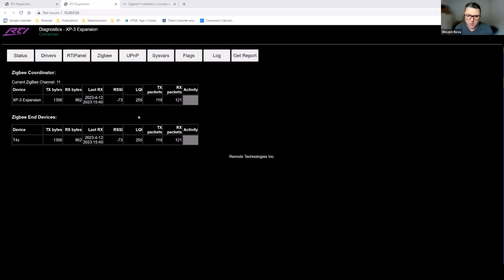In my own house, like most RTI employees, we have a lot of test systems going on. So theoretically, the Zigbee networks we're setting up could be interfering with the Zigbee networks that are part of our house. So whenever I look at LQI on my regular network, I might see a weird number because my test network is kind of overlapping with that real network and therefore causing packet loss. So, in that situation, there's nothing I can really do unless there's a real issue, but kind of know where you stand.